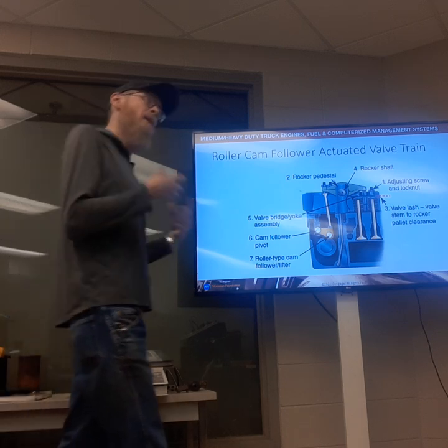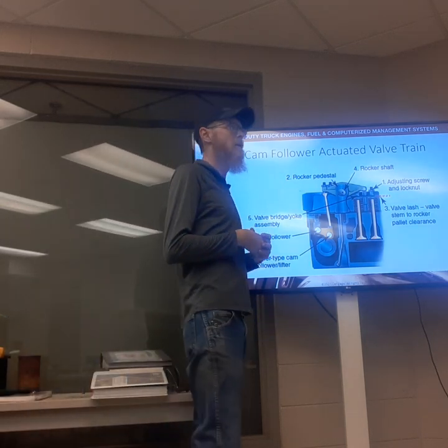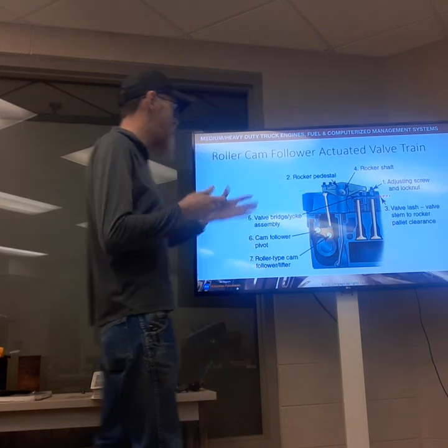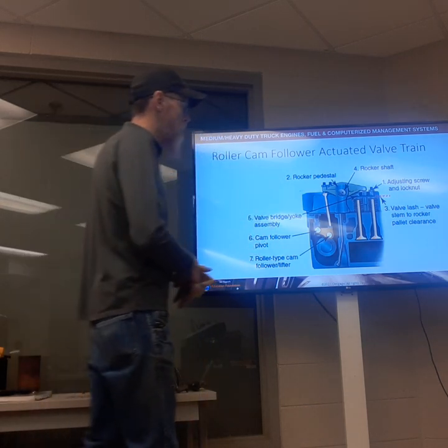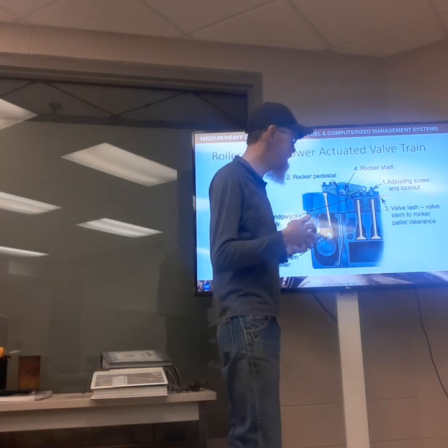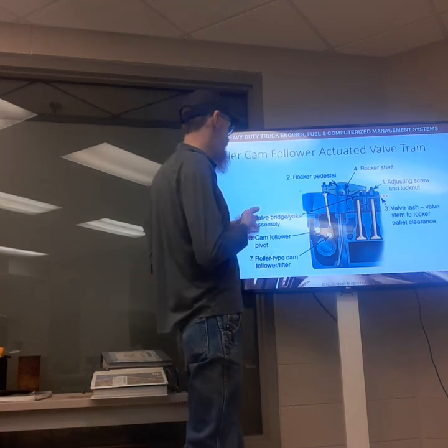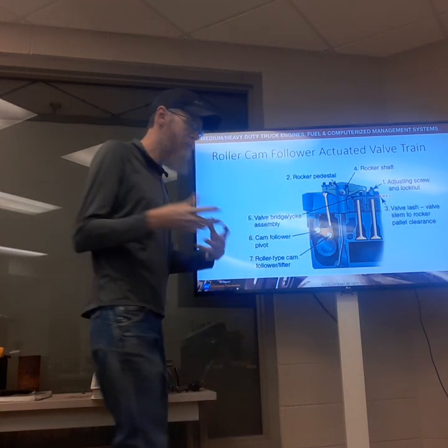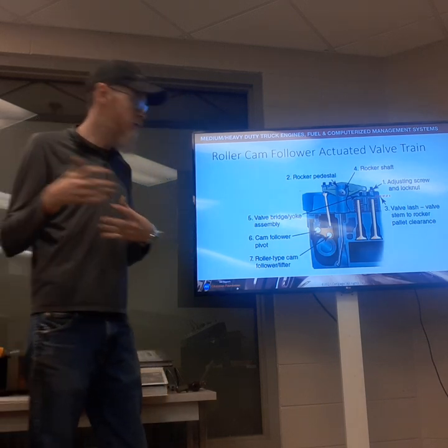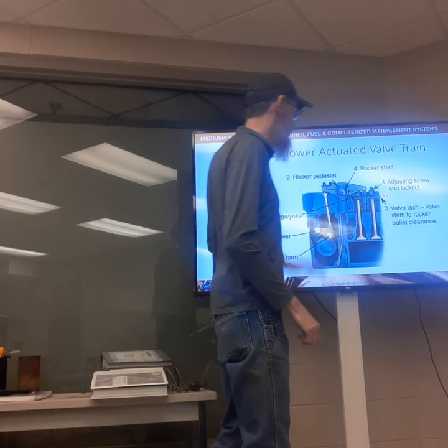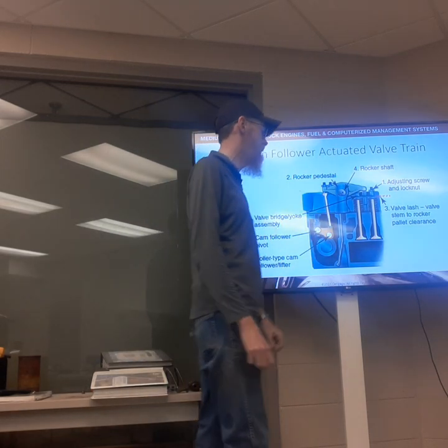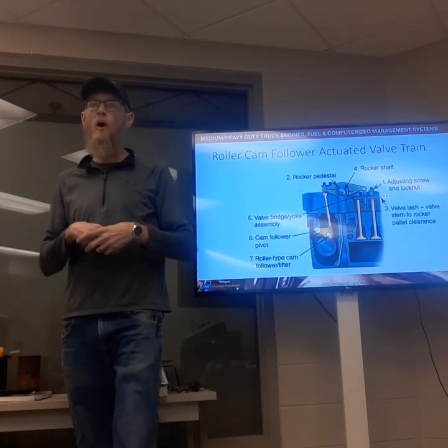There's not too many engines in service today that are a pushrod design anymore. In modern engines, we've gotten rid of the pushrod because, like I mentioned in the in-person lecture, we took that camshaft and moved it from the engine block up to the cylinder head, and that's what we refer to as overhead cam.